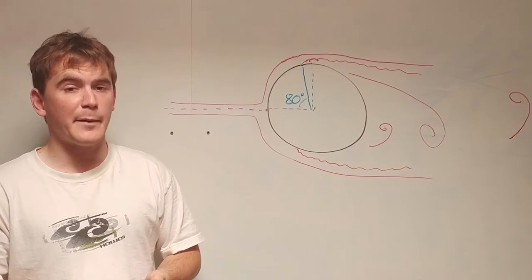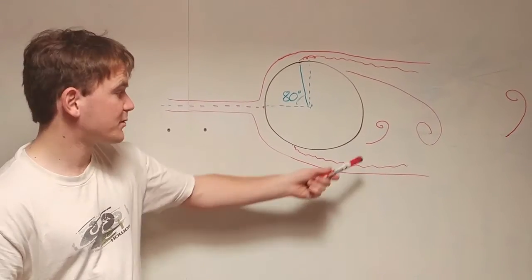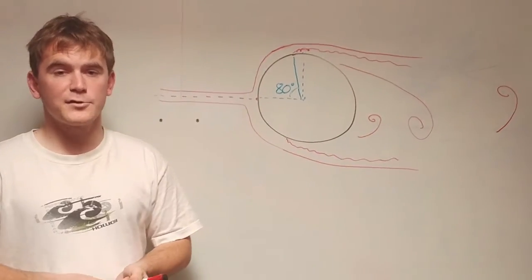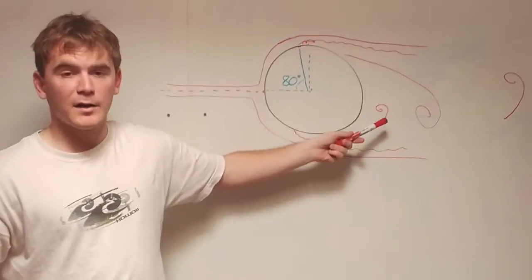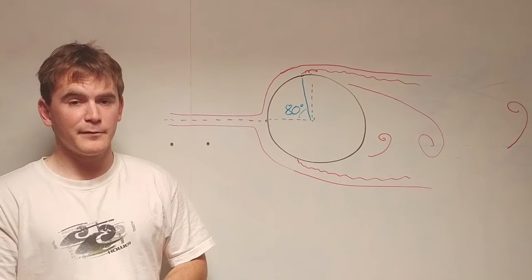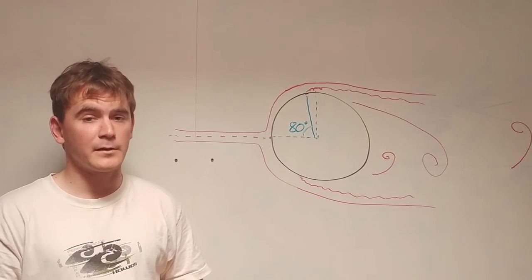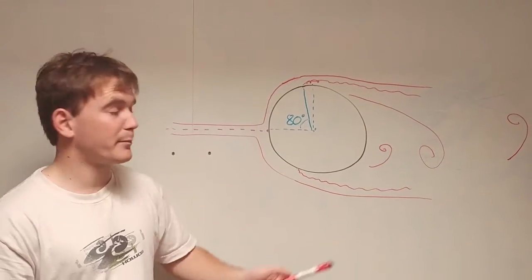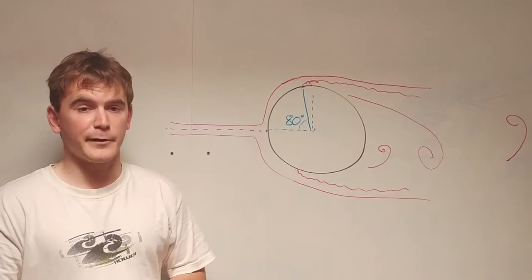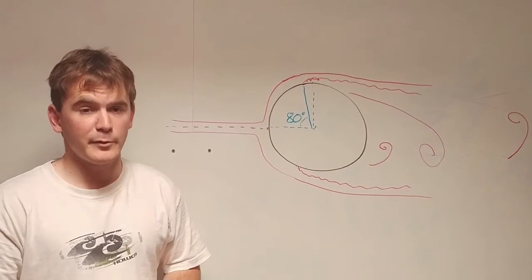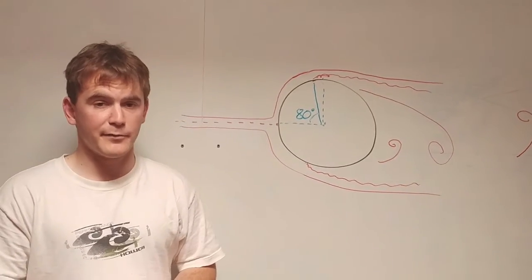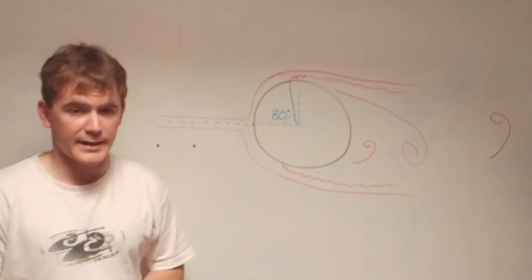any pressure difference between the top and bottom locations results in the accumulation of a discrete vortex. This then travels from one separation location to the other, oscillating back and forth with a variation in pressure. Vortex shedding is a function of Reynolds number, such that at low values, the vortices experience minimal oscillation. As Reynolds numbers increase, the pressure differences become more pronounced, resulting in higher frequency oscillations. Eventually, however, the turbulence of the flow overcomes the orderly nature of the vortices, thereby reducing their prevalence in size.